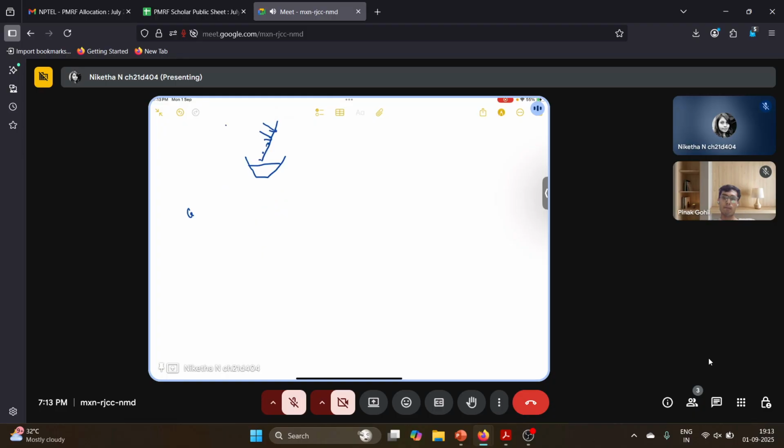And then there is the grit chamber. A grit chamber, like I said, is like a huge sedimentation tank where particles like sand, silt, small pebbles, usually solids which are heavier than organic solids, or metal pieces are allowed to settle.